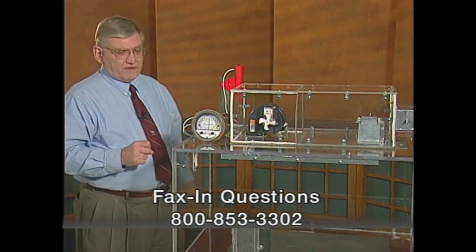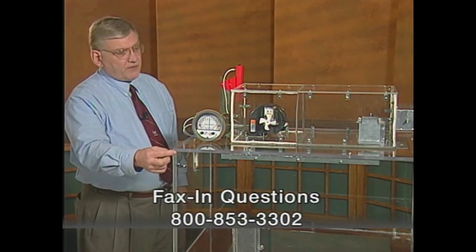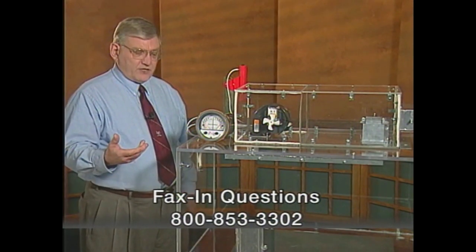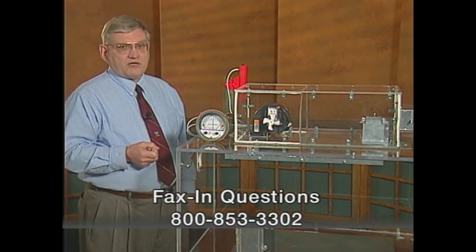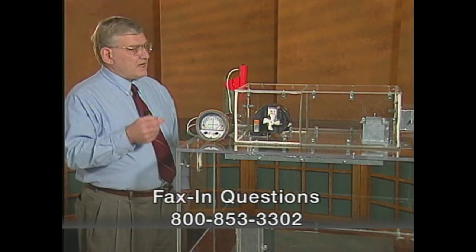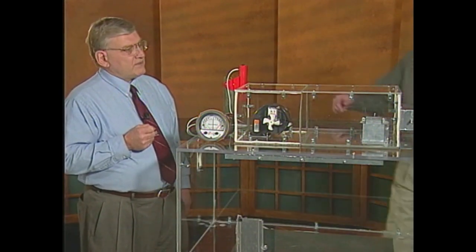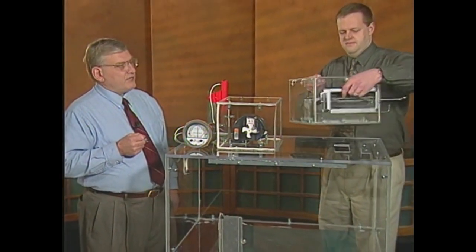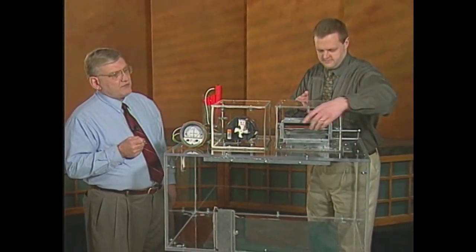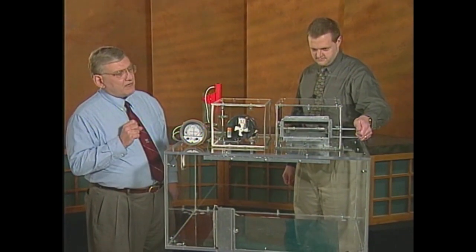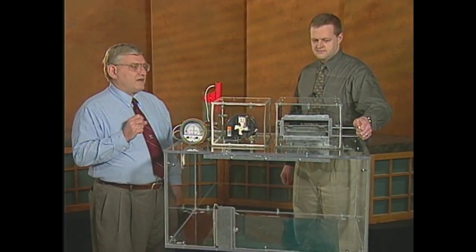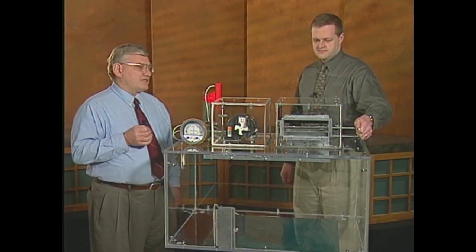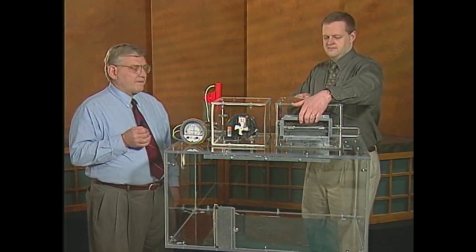Sealing the building was a real issue. The plenum area, particularly around the top, becomes a concern because it's a leak rate for exfiltration or infiltration. Just got to watch that in your building. On the mixing box, we had some very small low leak dampers built. These are very miniature versions of what you might see in a real rooftop or an air handler. Basically a single parallel blade damper, low leak seals around the damper. And John's demonstrating how they operate.